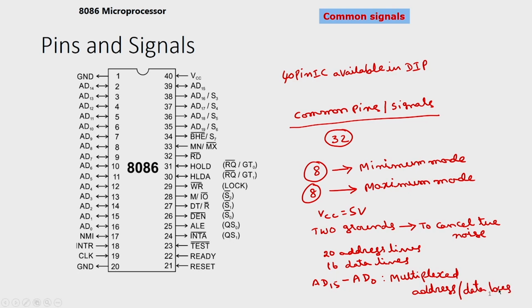The reason for multiplexing these signals is that we can reduce the number of pins. As the number of pins reduces, the area reduces, power reduces. Even if you multiplex this address and data bus, the function of the microprocessor will not be affected. If I split it into 2 parts, this is A15 to A0, the lower order 16 bits of address, and D15 to D0, the entire 16 bit data bus. So, when will this multiplexed bus be used for carrying the address, and when will it be used to carry the data?